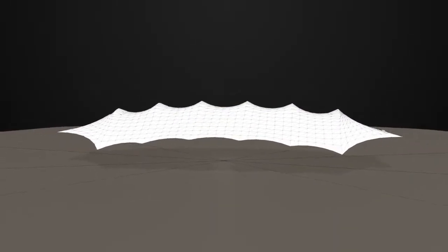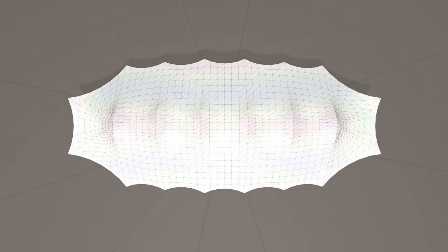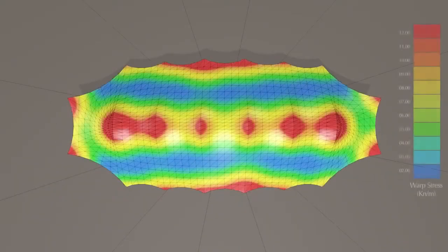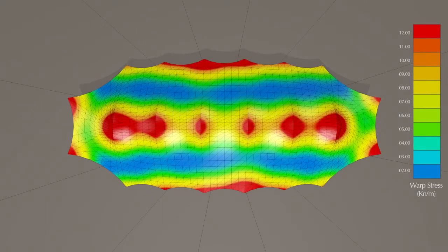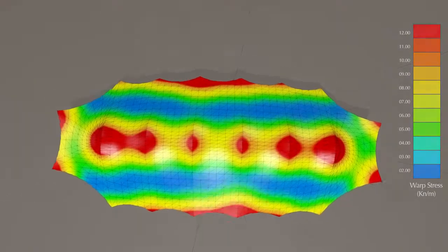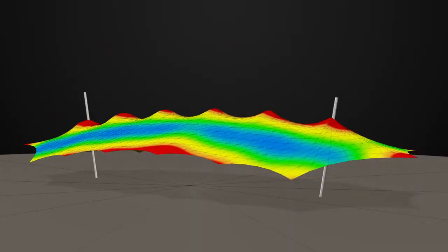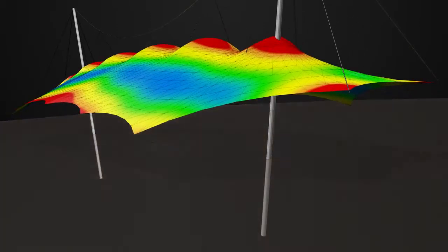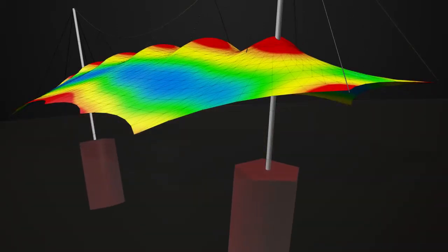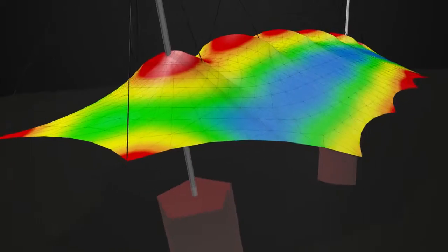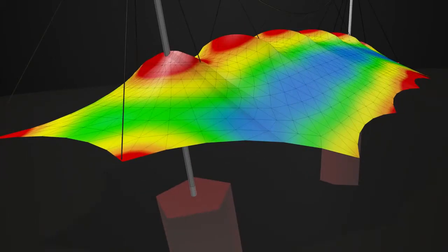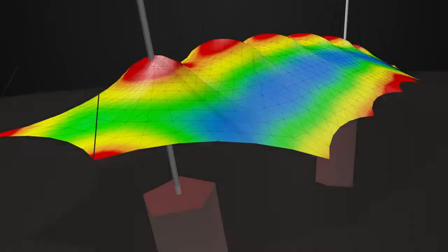As part of the preliminary design process, a load analysis is derived from a computer-generated form-finding model. This provides the typical load size and direction. Then, incorporating a factor of safety, an engineer will determine the design of the supporting structure, the size of the foundations, the required material strength, and the necessary tension. The boundary details are then engineered to maintain the tension and accommodate the movement that may be generated at the canopy extremities.